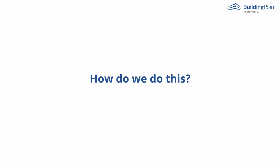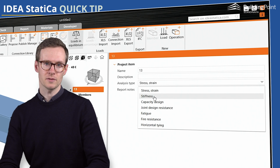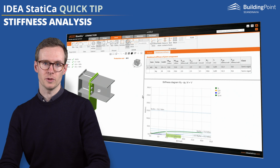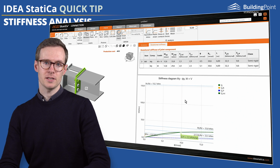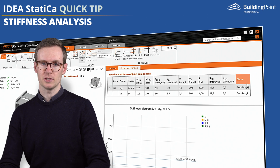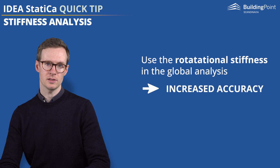So how do we do this? IDEA StatiCa has a stiffness analysis function that helps you determine the stiffness of the joint and thus validate the global model setup. The output and results of the stiffness analysis is the moment rotation diagram and a table with several values. Based on the curve and a selected standard, IDEA StatiCa assigns a stiffness class to the joint, pinned, semi-rigid, or rigid, and this information can be used as feedback to your global model to further increase the accuracy.